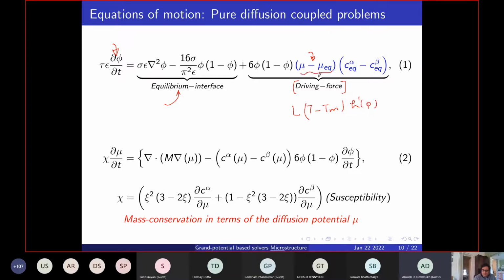And in some sense, as I said, the temperature and the chemical potential share a nice analog, and thereby you are able to directly see the extrapolation from a pure material case. And because this is a dynamic variable now, you have to transform your mass conservation equation from the composition to a chemical potential, which is easy to do. It is just a reformulation, just like you solve for the temperature instead of the internal energy in the case of the pure material. So that's the same analogous transformation, and one can see this quite readily.